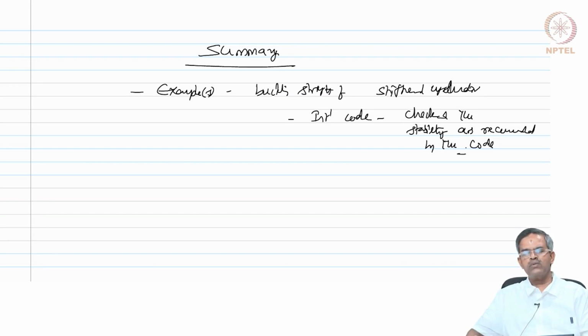We understood that the stiffness matrix formulated for a stability problem is more or less similar to that generated for a simple analysis of a statically indeterminate structure, provided we remember the order of the labels and the stiffness matrix.